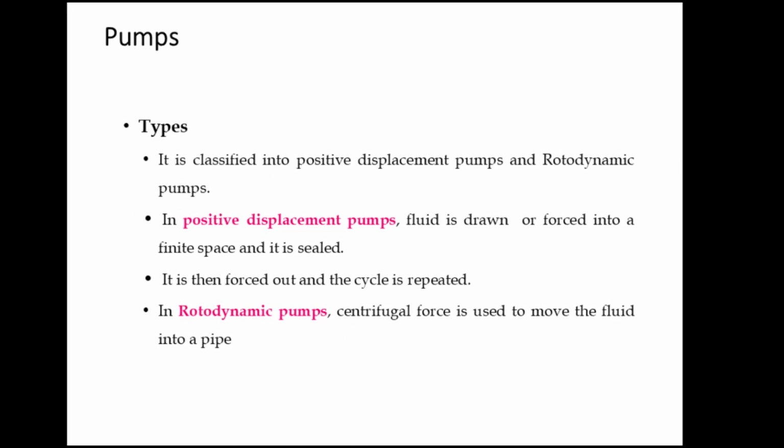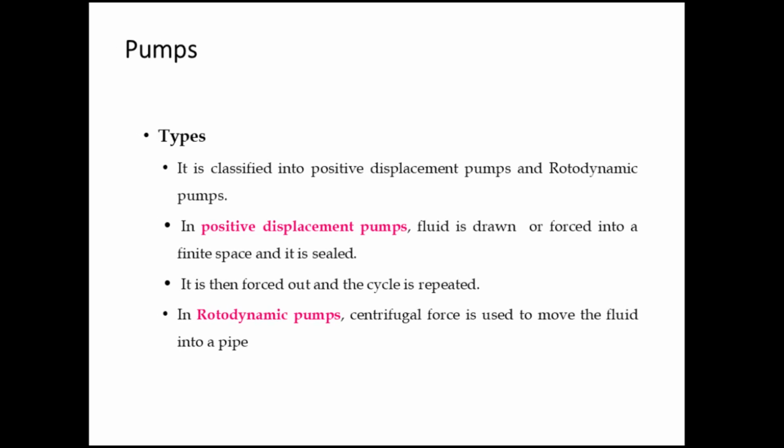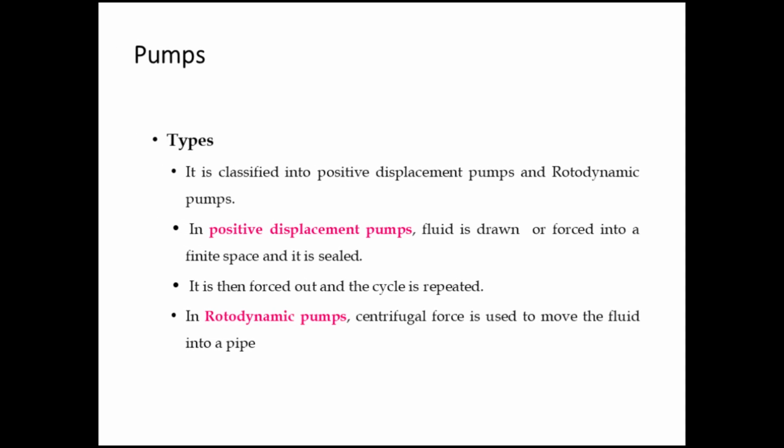Pump types. Pumps are classified into positive displacement pumps and rotodynamic pumps. In positive displacement pumps, fluid is drawn or forced into a finite space and sealed. It is then forced out and the cycle is repeated. In rotodynamic pumps, centrifugal force is used to move the fluid into a pipe.